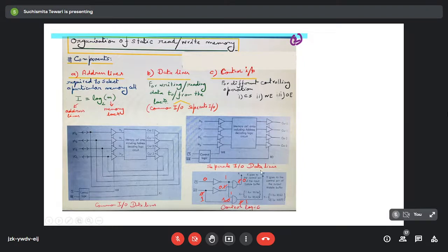Instead, since here it is now getting the logic 1, it is enabling this tri-state buffer, that is, it is connecting this data pin with the output data bus like this. So in this way, read and write operations can take place in alternate fashion. When it is 0, the write operation is taking place. When it is 1, the read operation is taking place. So this is the whole mechanism of how data can be written or retrieved from a particular memory cell or from a memory unit.